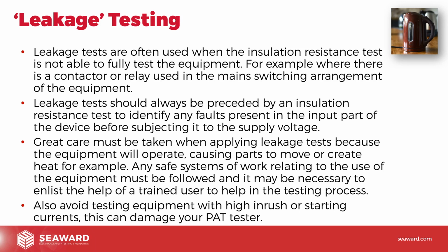I've also seen people test grinders. I've seen somebody test a 9-inch grinder where they just left it on the desk with it switched on, because they want the on switch switched on. They got to the leakage test, and it said, is it safe to turn it on? They just went, yes, hit the button, and the grinder spun round and shot off the desk onto the floor. So those sort of things, we've got to be very careful to avoid when we are applying these tests. So always think about the precautions before you apply the test voltages, because it could be too late afterwards.